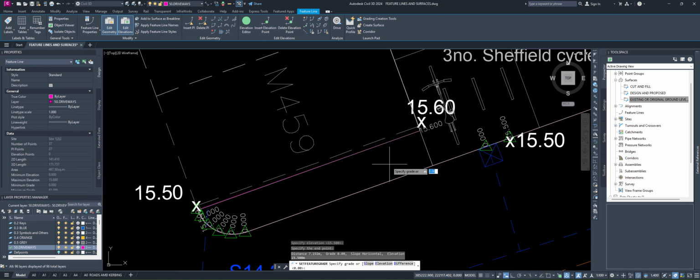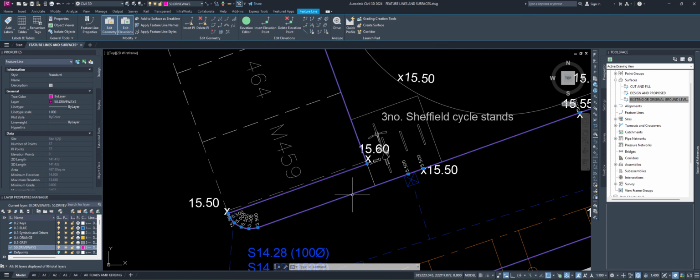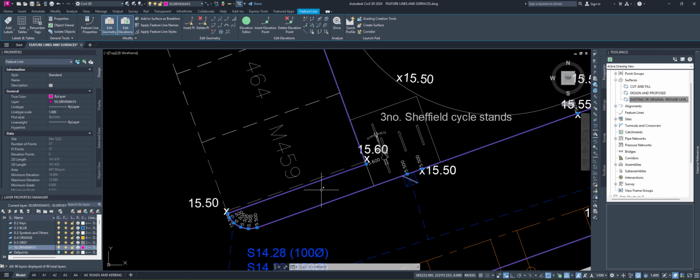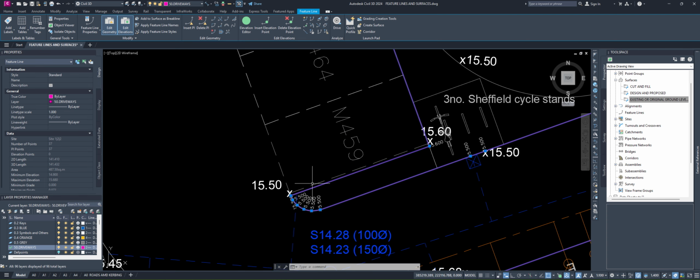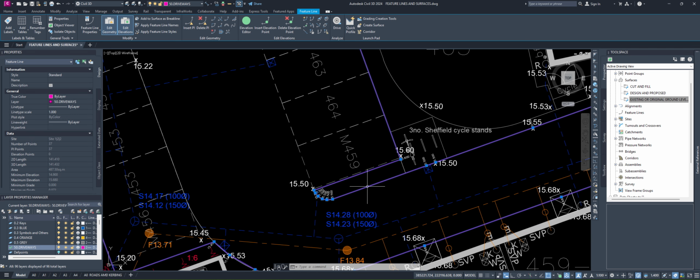The moment is 0 because we are at 15.500 here and 15.500 here. Okay, it doesn't really work well. What we can do, let's finish that. Let's click OK. It's completely flat level here. We don't want it to be completely flat. We want to create just a little high point here, which is going to push the water this way and then this way as well. Both ways.